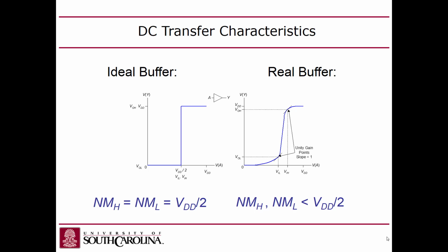So once you know where your VIL and your VOL are, you end up with what's called a noise margin, which is the difference between those two. It's basically how far the input can deviate from what the output is for a low and a high. That's how much noise you can add to the wire without affecting the behavior of the circuit, without screwing up the bits in there. You guys with me? Make sense? So that's the idea.